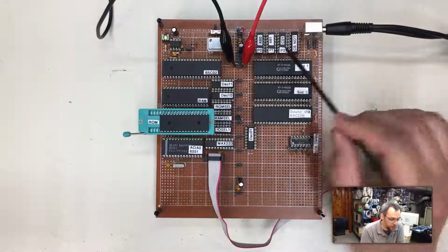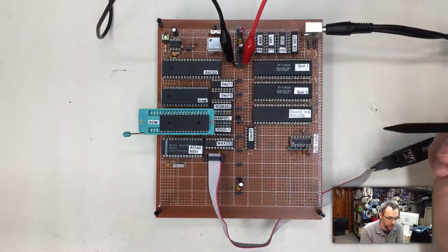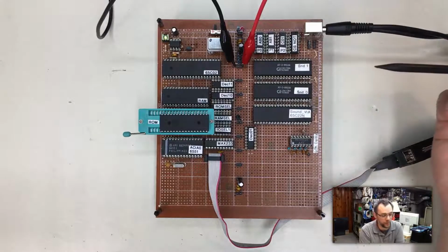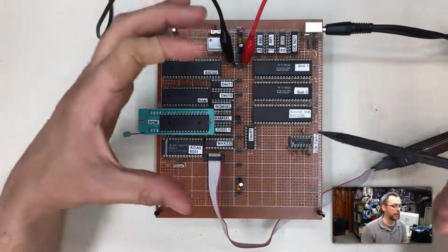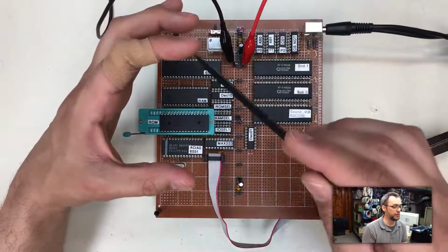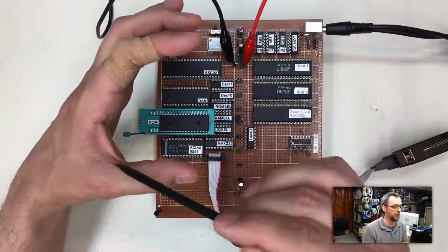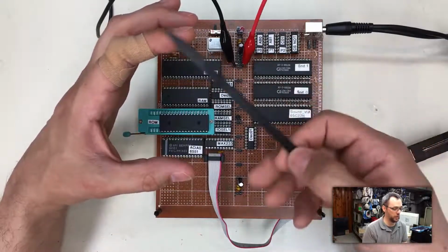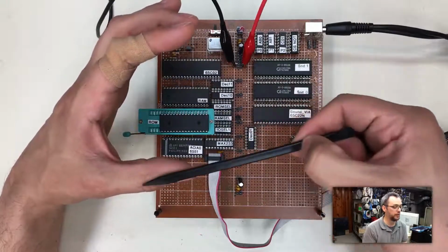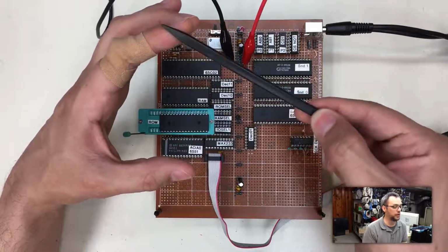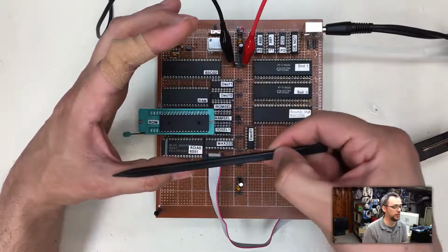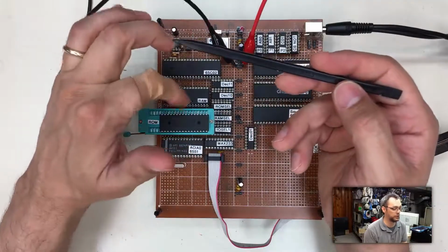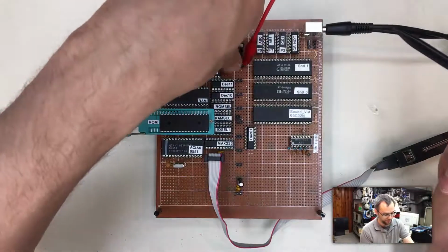It also has the ability to disconnect any of the individual terminal positions or the wiper position of those potentiometers. So a potentiometer is like this, and it's got one end, the other end, and basically this is a big resistor, and this is terminal A, terminal B, and consider this as a wiper. And as you turn it this way, the resistance on one side grows while the resistance on the other side decreases.